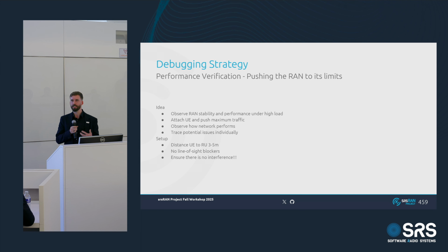And then we can trace potential issues individually. The setup, usually what I do, is I set up the UE 3 to 5 meters away from the base station, with no line of sight blockers, and very important, make sure you don't have interference.